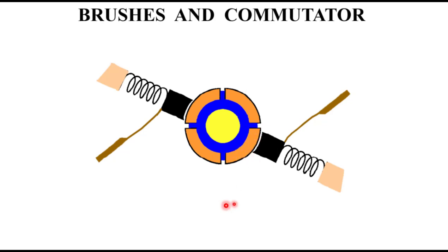The brush conducts it onto the armature through this commutator. The coil runs through the winding. It comes out on another commutator segment into the brush, and I've got my loop. This goes to the other side of my power supply.